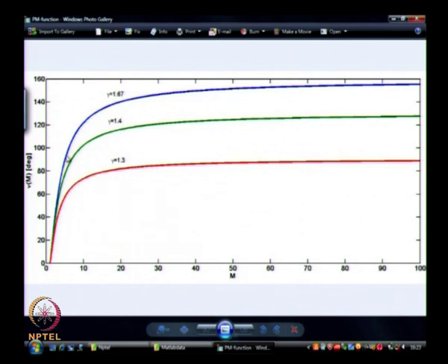What we are seeing is I have to turn the flow a lot to accelerate the flow if I have a less compressible gas, gamma equal to a very high value. When I have an easily compressible gas, when I change the flow direction, that is I am sending an expansion fan, I need to turn it by a small angle to increase Mach number very highly, that is a special effect of compressibility here.